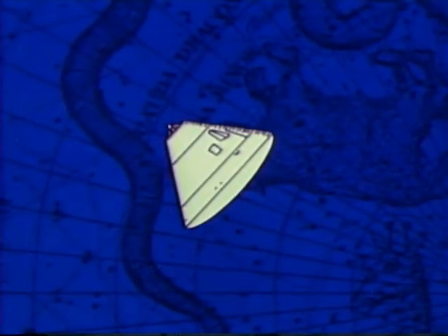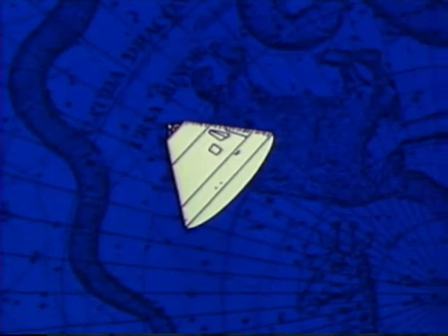Proper alignment of the spacecraft is determined by the onboard computer from data received from the tracking network prior to entry. After proper alignment, there will be control only in the roll axis, pitch and yaw being stabilized by aerodynamic forces.